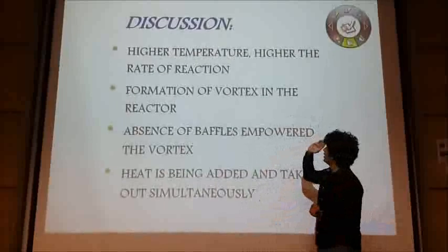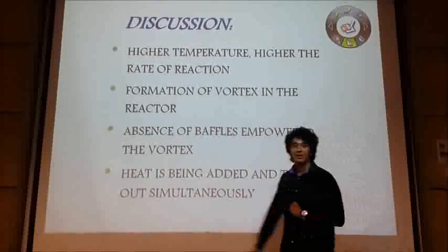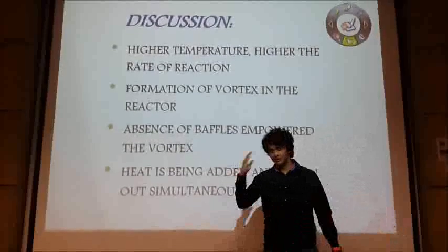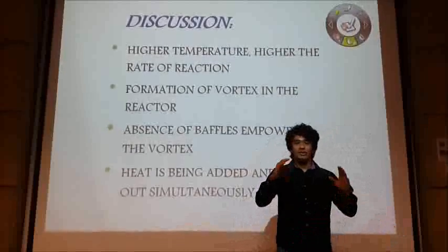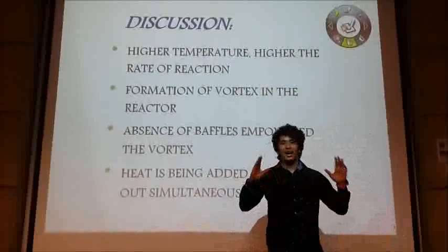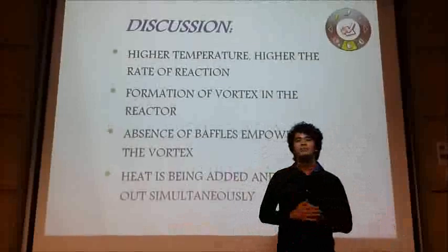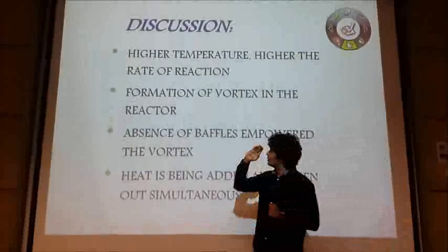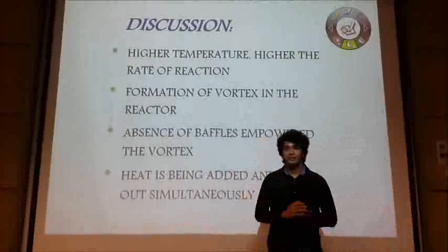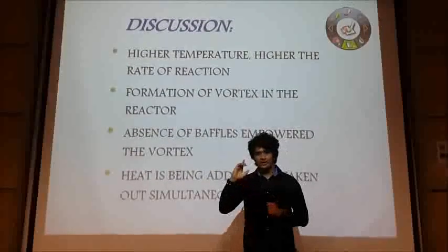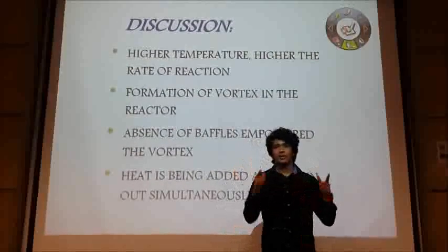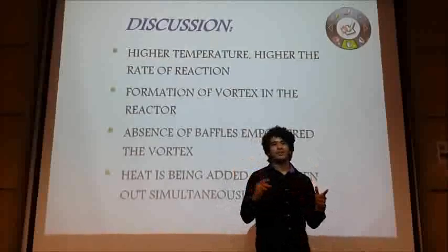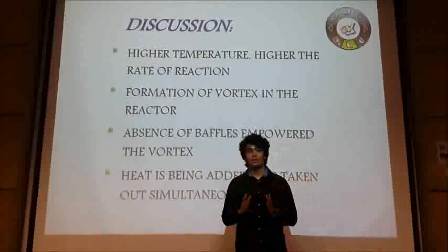Same case goes over here. The higher the temperature, the higher the rate of reaction. For our case, the saponification rate was higher when we used a higher temperature. So let's move on to the formation of the vortex in the reactor. The formation of the vortex played a role in our rate of reaction. It gave a negative effect actually. It made our reaction time longer.